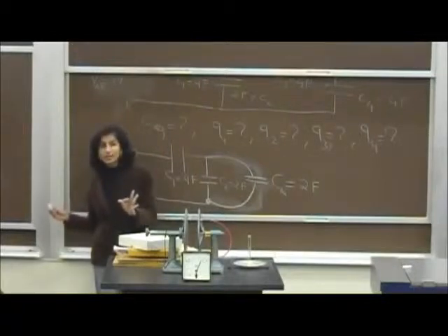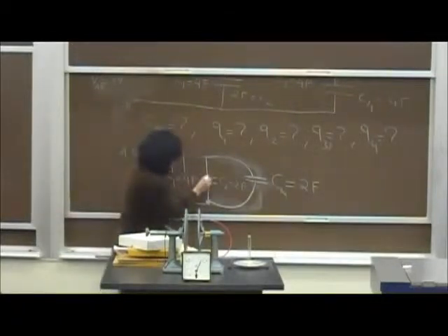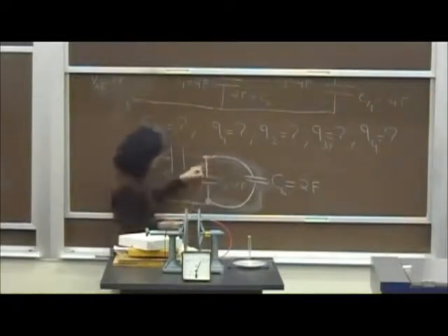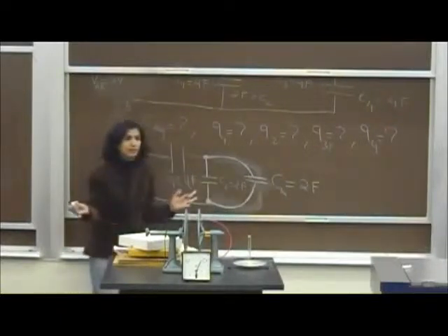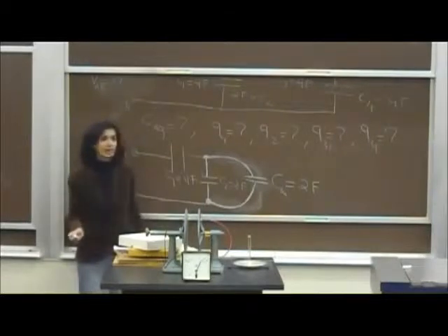One way to figure out that they are in parallel is to look at their edges. Look, one end of this capacitor is connected to this wire, and it's meeting one end of this capacitor at this end, and there's nothing in between them. Let's check the other end. This end has this wire connected to it, and this end has this wire connected to it. Hey, there's nothing else in between them. That's good. That means these two are in parallel, right?